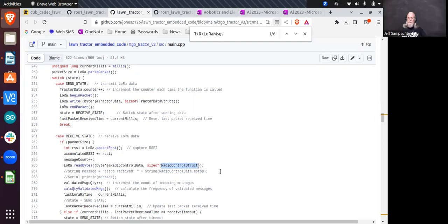Yeah, the first thing I would do is print out the time when you receive them. And where you're comparing it to 1 second and it's failing, print out at that time how far off it is. Is it off just a little bit, or is it off substantially? If it's off substantially, then you've probably got a code problem somewhere.